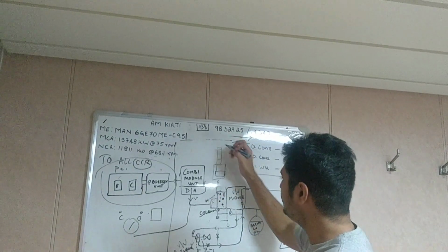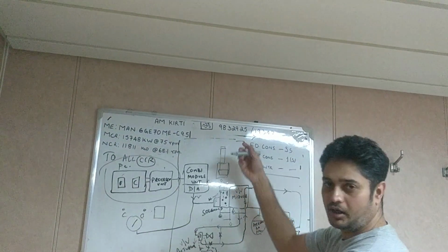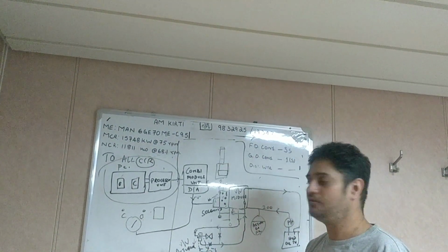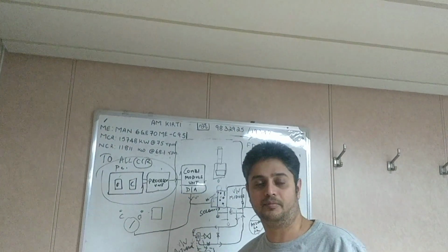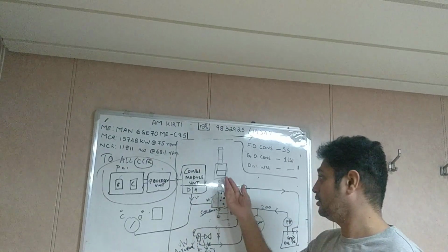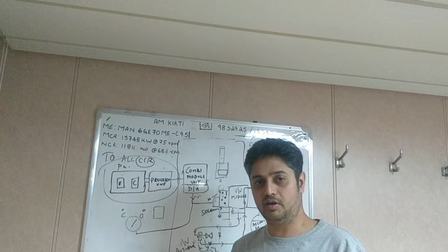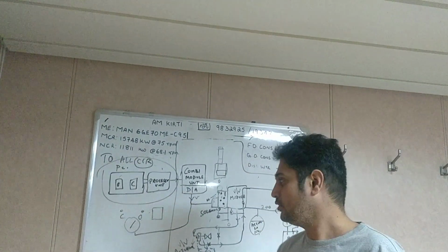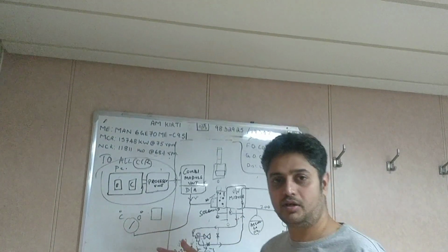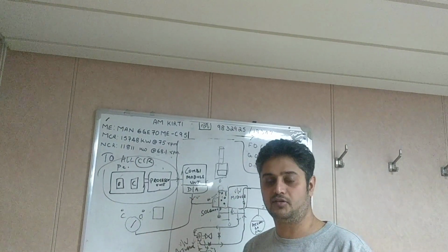So what you do is see whether you can put a spanner here and see if you can do something. If it is a small valve, you can try that. If it is a big valve, you have to overhaul it. There's no other option. Overhauling a big valve in the duct keel is a very major task. So these are the troubleshootings. These are the different types of troubles you can experience in the system.